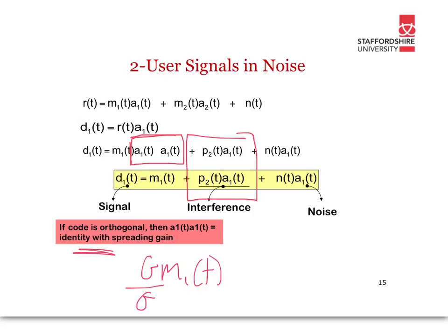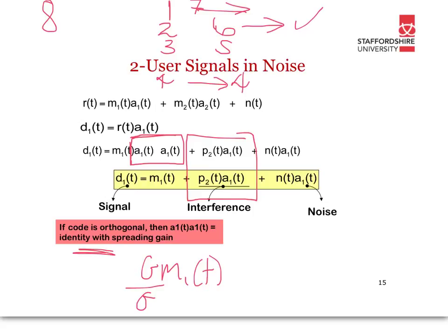Previously we had a gain of 8. What this means is if one error was received, or one bit was received in error of those 8, then we would still get the correct results. If 2 bits were received in error, then 6 would still be correct, so we'd still get the correct result. If 3 bits were received in error, then 5 bits would be correct still, and we'd still get the correct result. However, if 4 errors were made, then we'd have 4 bits in error and 4 bits correct, so we would possibly not get the correct result.